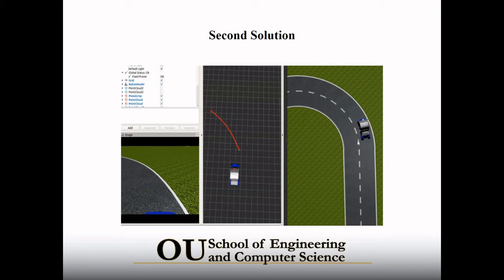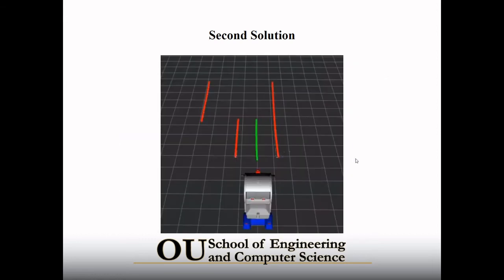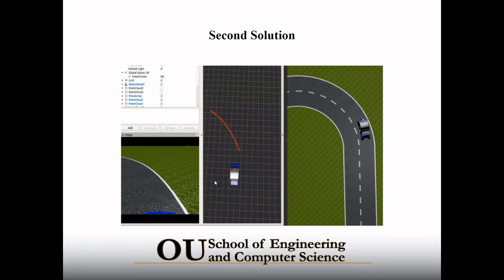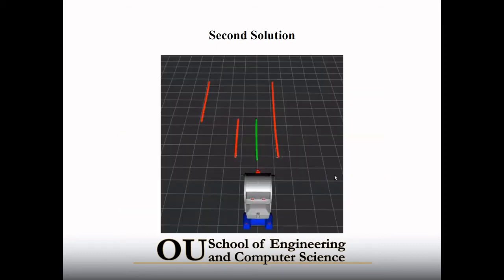So we had to find a way to trade off between not allowing this to happen and violating the center line by a bit. How far the first point of the center line is from the car is controlled by a config variable, which is the look ahead. This problem happened when the look ahead is 3 or even 4, but with 4.3 we got the best performance.